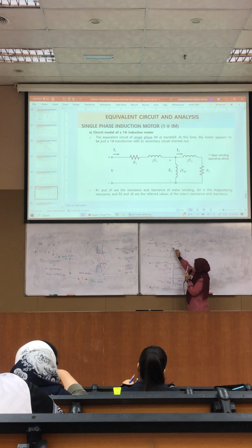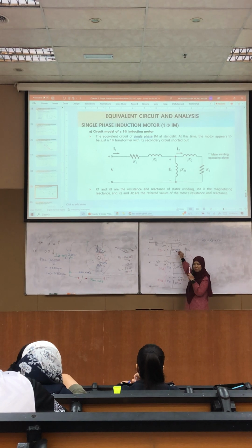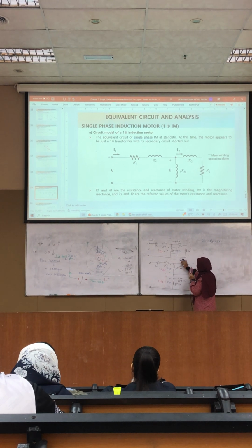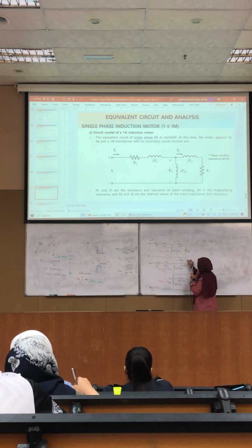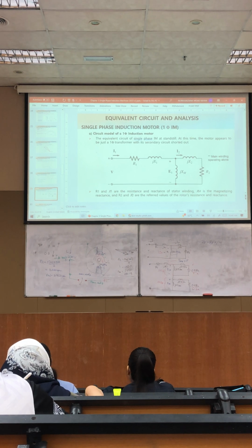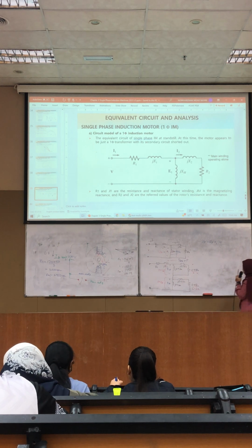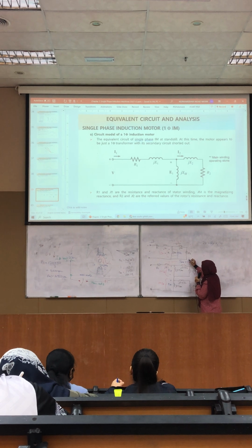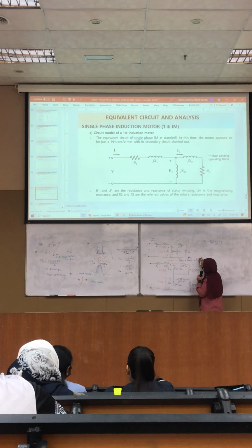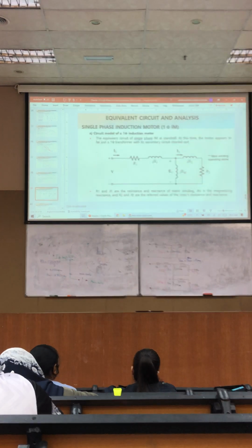If you notice that we don't have any RC, RC is not mentioned for this one because the core losses, P core, will be included with P friction and windage, P stray, and it is called P rotational.